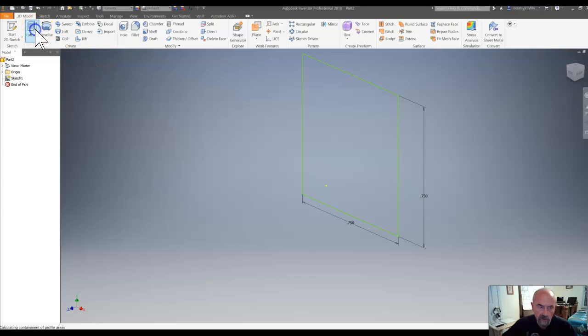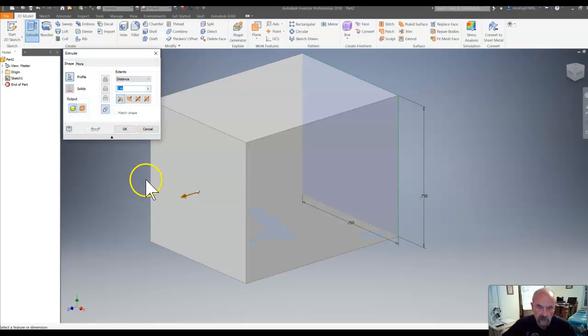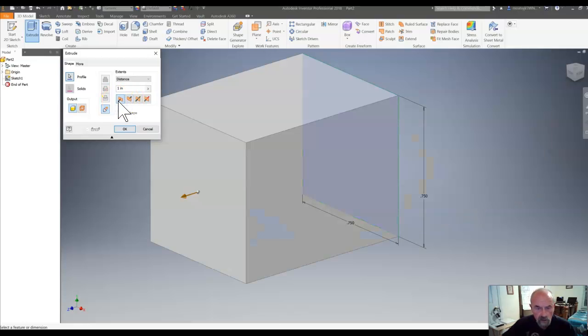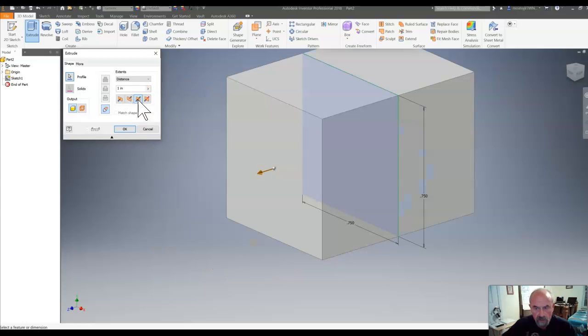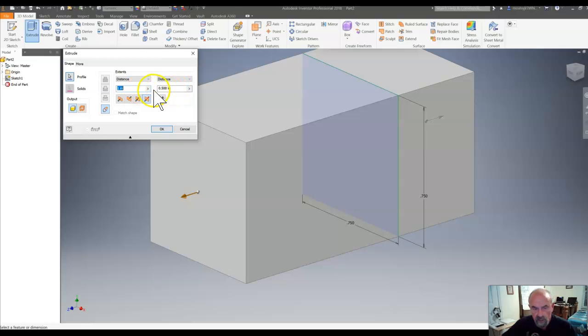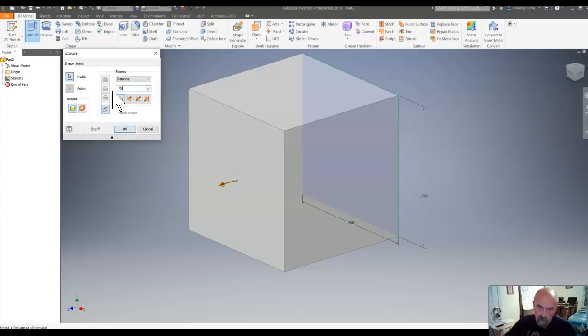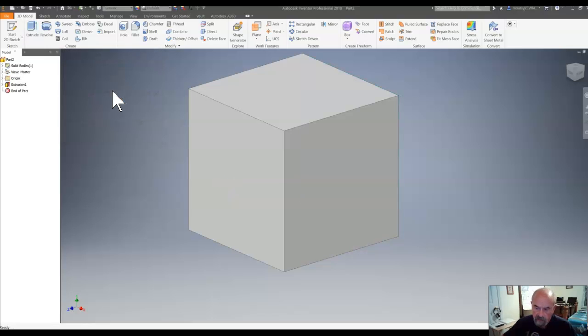And then I'm going to come over to my Extrude feature. It automatically pops out because it only has one choice at this particular point. We only have one closed profile. Although I can have it go away from the sketch or towards me from the sketch, symmetrical, split it in the middle, or asymmetrical and give myself 2 distances, I'm going to stick with 1 for now. Set that distance to be 0.75, 1 square block. Click OK. So now what I've got is one of my wooden cubes of the puzzle.